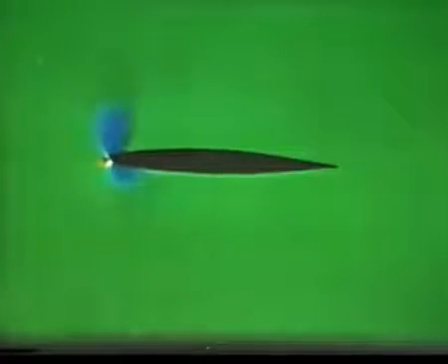The colors show regions of increasing and decreasing density. The red area at the leading edge is the stagnation region, where the air is being slowed down and becoming denser. Immediately behind are 2 blue areas where the rate of speeding up is greatest, causing a reduction in density. This diagram will remind us of what's happening.